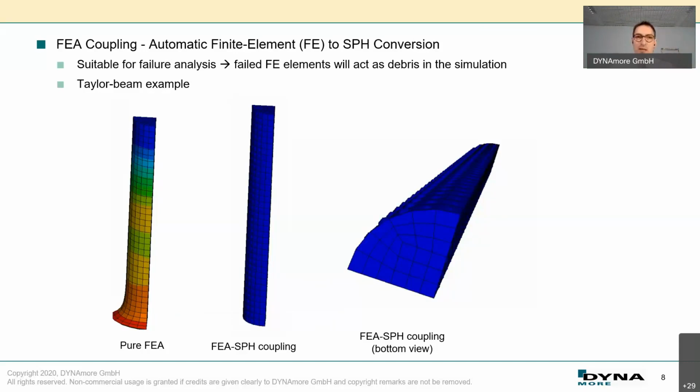I have to check in the manual. I don't remember exactly, which creates the SPH elements. You can define how many you want to have. If it's one SPH per solid, maybe you want to have 2, 3, 4, depends on you. But in any case, they're already there, and the information like stresses is transferred to the SPH elements.